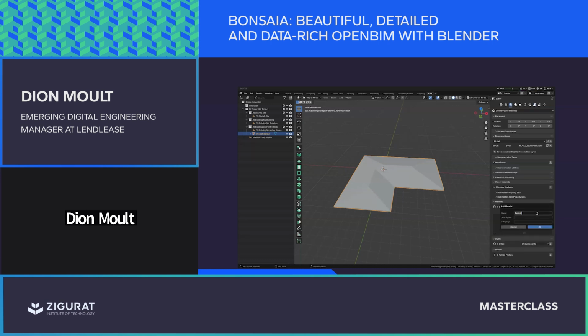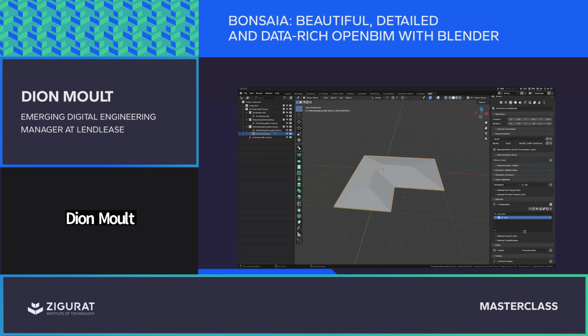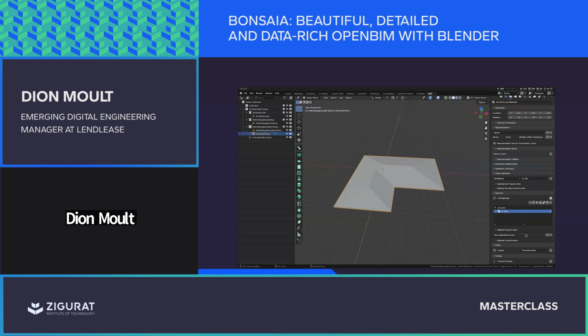So for example, I can have an in situ concrete, and I can have a material in here, and that can have data. I have to check what version I'm on here, but I can go and assign the compressive strength of that, whether it's in situ or precast, and the strength class of the concrete.